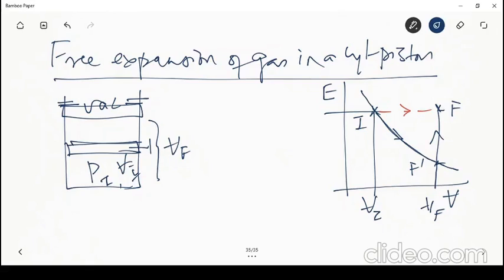So then the entropy change for this process is 0, and the entropy change for this process is delta Q by T, and this delta Q is equal to delta E, and if delta E for the gas is the mass into specific heat into T, so if dE is mc dT, so if I take out the mc and integrate dT by T, I get log Tf by Tf prime, and that multiplied by mc will give me the Sf minus Sf prime, which is also equal to Sf minus Si. So exactly in the same fashion as the previous case, this can also be evaluated.